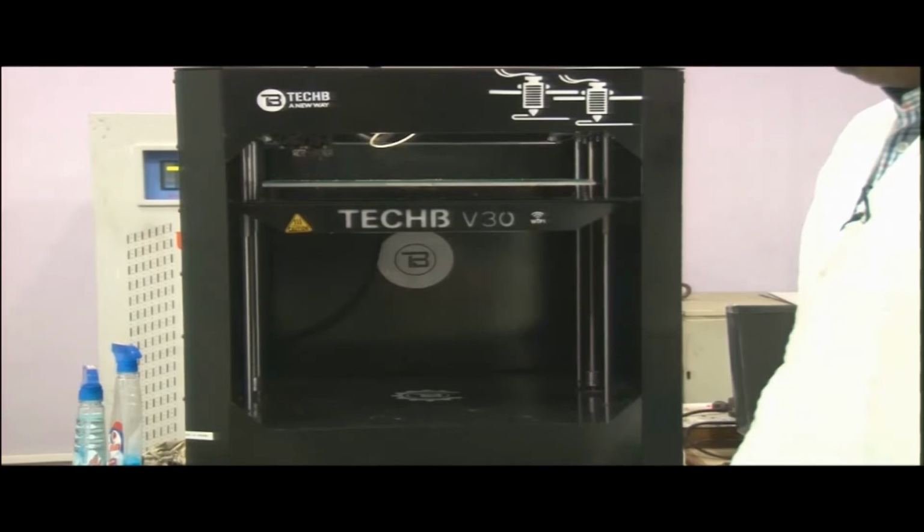About FDM and SLA: the FDM machine produces products with precision, but the precision level in SLA is higher. Higher resolution objects are more possible to produce in SLA because resin is there. The resolution is primarily determined by the optical spot size either of the laser or the projector, and that is really small in SLA. In FDM the printer resolution is a factor of the nozzle size and the precision of the extruder movements. That extruder we will discuss in this demonstration as well.